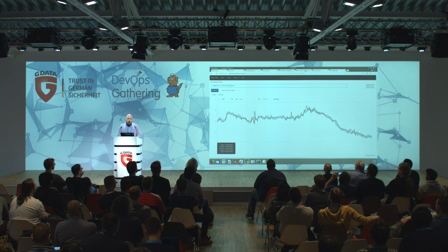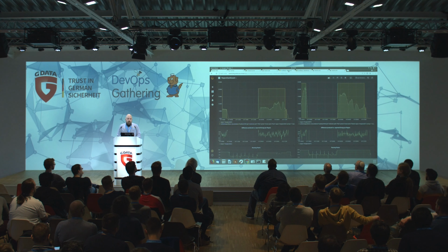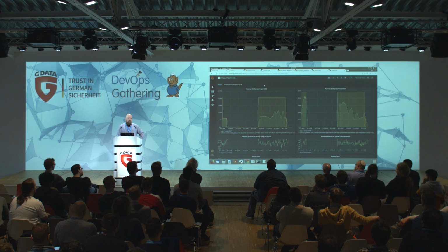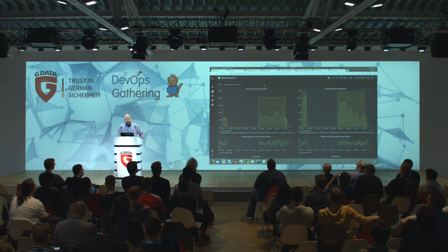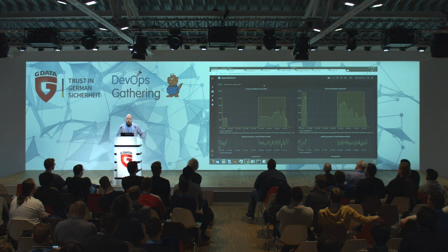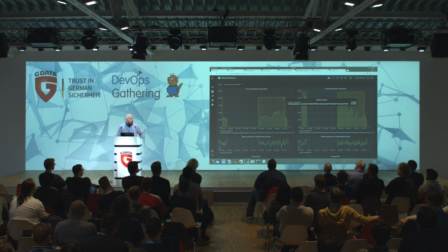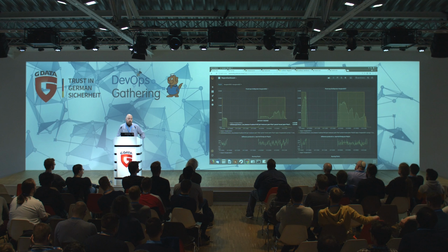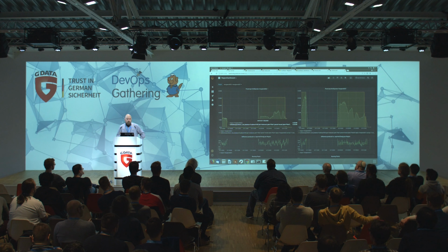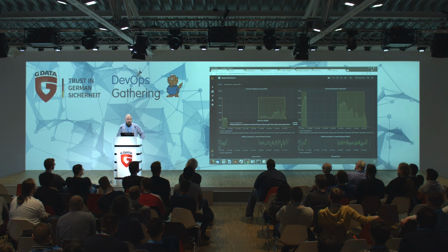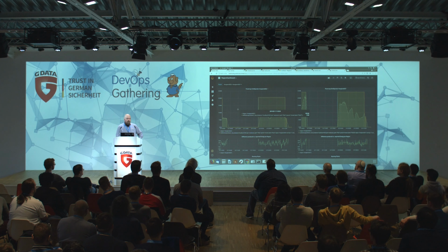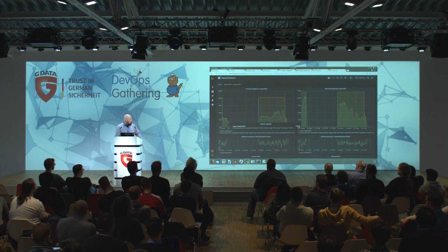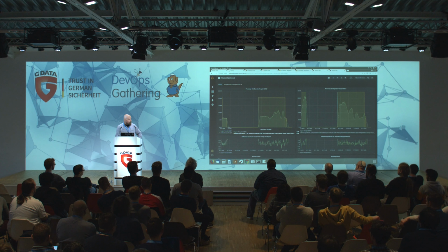And we also set up dashboards in Grafana. As you see here, this is a region dashboard. We've got 2 regions here. Unfortunately, the power grid in Germany is not strong enough to cope with the renewable energy. The yellow curve here is the desired cap from the network operator. So here, the network operator gives them the signal: you may only put 6 megawatt into our network, and then the wind turbines are automatically scaled down. And the green line is the actual line that is scaled down to.